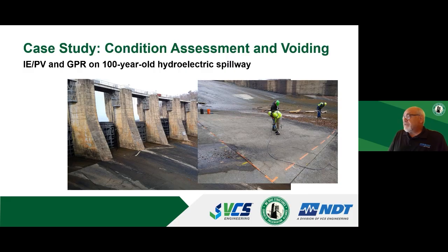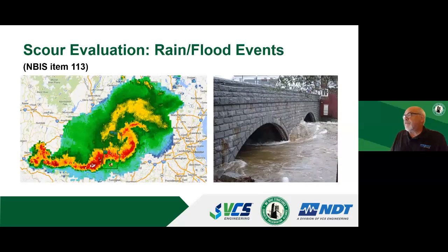Another larger investigation, we did a couple of test areas of a large spillway for a client. Wanted to validate our testing methodology. We got the condition of the slab, and some limited plans say the slab might be on rock and it might be on rubble. It was on rock in places, it was on rubble in places, in some places it was on nothing because the rubble had washed away. So we were able to, like I said, power wash a couple of different test areas and do our testing. The condition of the slab and the presence of voids under the slab were the objective for that one.